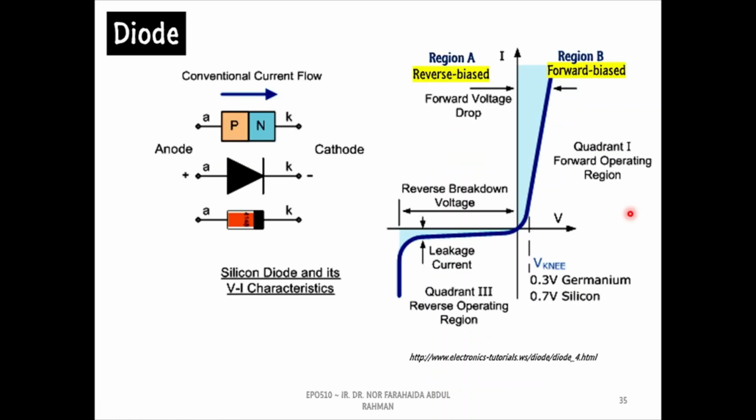We will start our discussion with the simplest power switches, which are diodes. Unlike other power switches covered in this topic, diodes are uncontrollable devices. Thus, we cannot control their operation. A diode will switch from off state to on state and vice versa depending on the nature of the current flow in electrical circuits. If the current flows toward the anode terminal, the diode is in forward bias and it